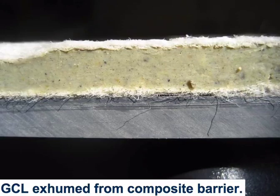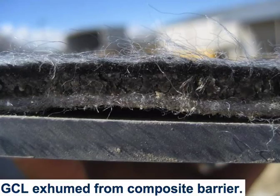So here's a photo of a GCL exhumed in the field. And this GCL has that nice hydrated gel structure that we're looking for. This is a good sign. This next photo is from a GCL exhumed at a different field site. And you see the bentonite isn't fully hydrated. In fact, it's only at about a 35% water content. And so we have that retained granular structure.